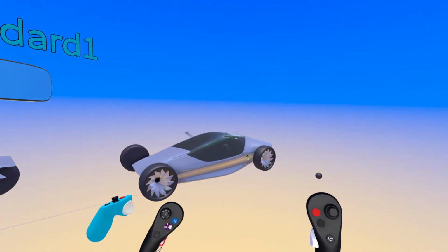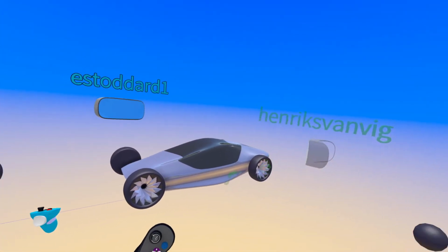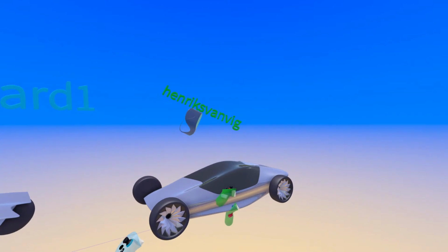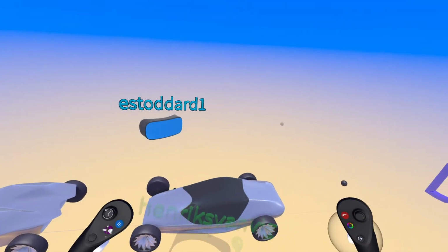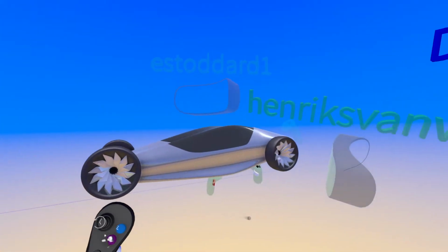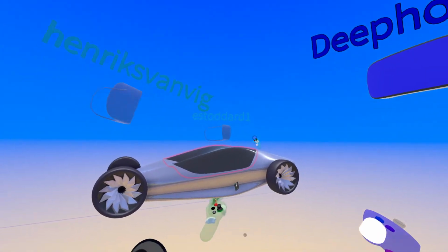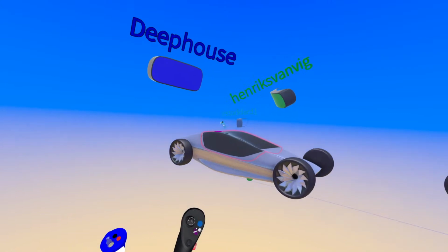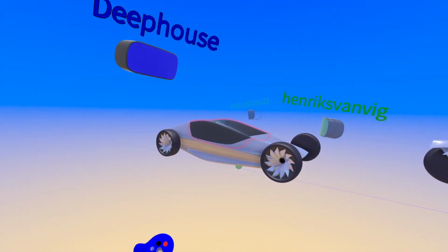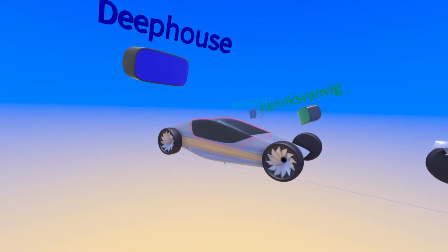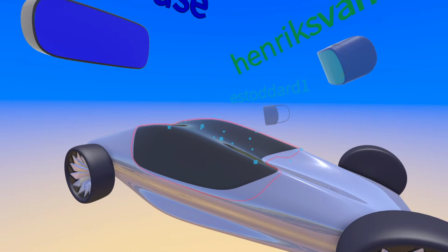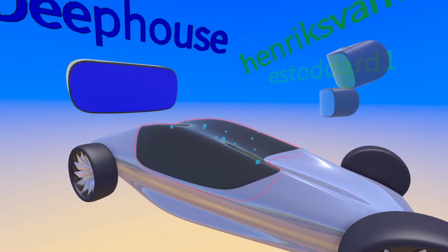But that's pretty comprehensive. You can see how closely I was able to match the original surface by using the thicken tool to create that slight lip, that slight offset between the glass and the body that all vehicles have. I can make it even smaller and tighter, right?